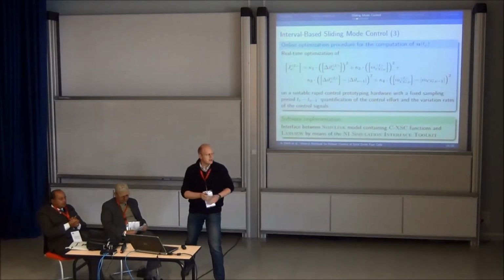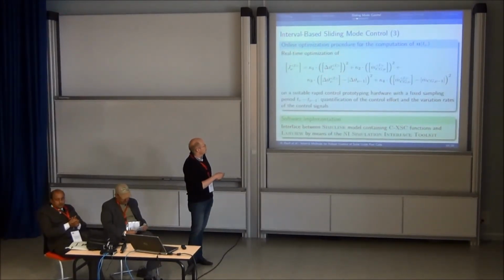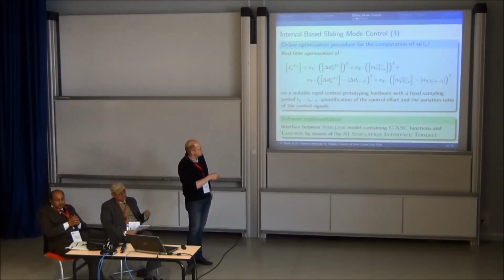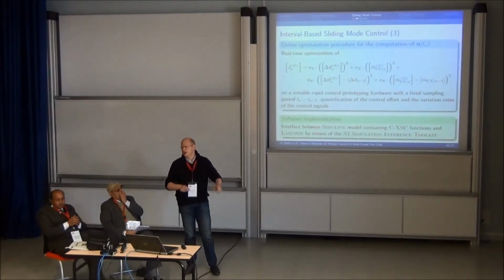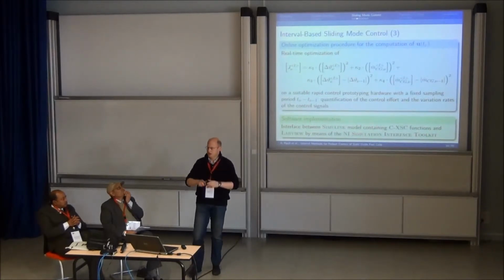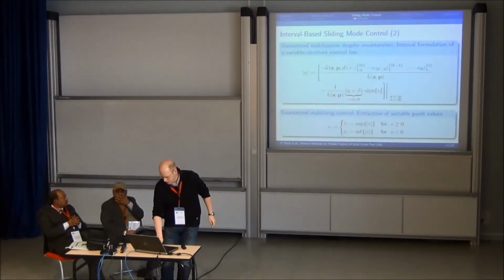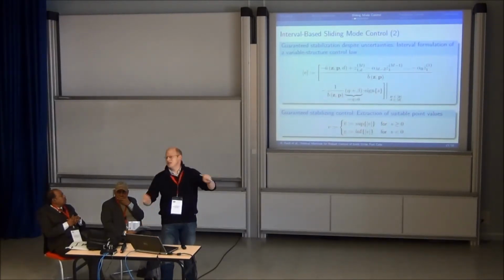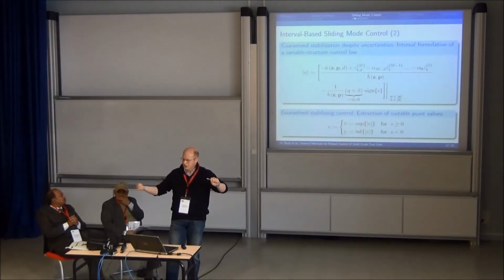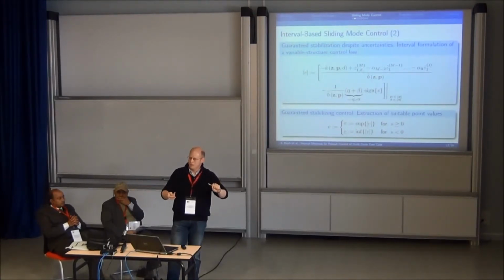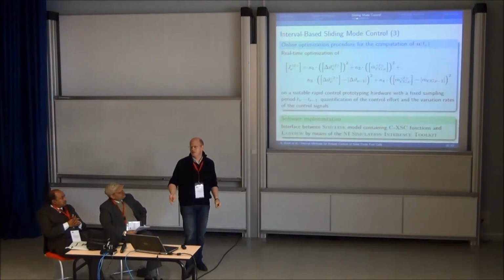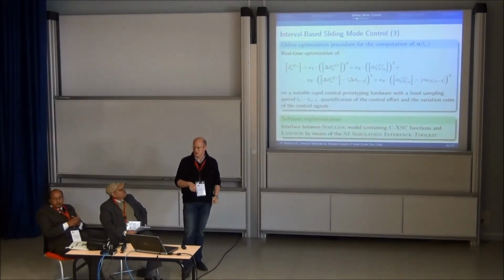Let's look here. Here you can see it. We have range constraints for the preheater temperature, and we have range constraints for the mass flow of the cathode gas. These are intervals that we know in advance. From these intervals, we only pick out intervals which fulfill the sign constraint that is described here on this slide using the Lyapunov function. That means arbitrary points within these intervals guarantee asymptotic stability. The only question is which point to choose from this interval in order to get energy efficient operating strategies.